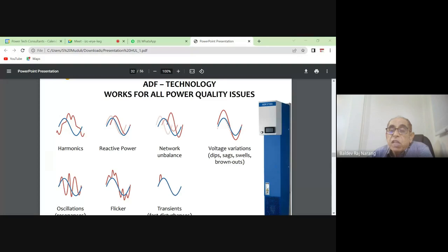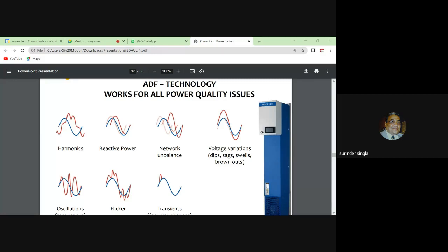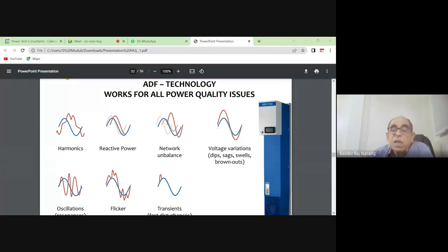So suppose we take it to 210 hertz, which is 5.67%. Then it will attract more harmonics. The harmonic mitigation will be better, and we will get a better result. Is there any formula, or are we taking the next range? There is a formula. This is derived from the formula only. You will get it, maybe I'll share with you. I think somewhere we have shown it in this also. Okay.